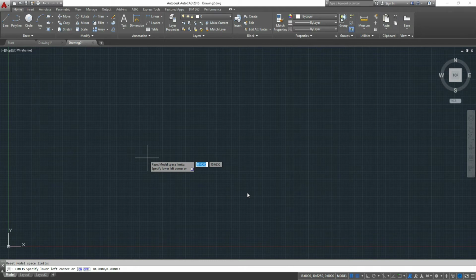But before that, I want to show you the different coordinate entries. There are 2 ways of entering coordinates in AutoCAD, Cartesian or polar. Cartesian coordinates are entered 1 unit at a time, separated by the comma. Polar coordinates are entered with the less than sign being the angle, so you have a magnitude, less than sign, at an angle.